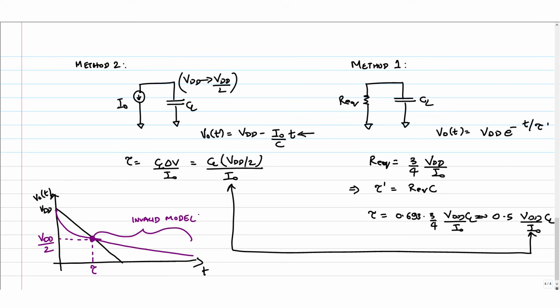The reason I am pointing this out is you will see that we use certain models in this course which are valid only in certain regions of operation. Outside that region of operation, if you ask me what the value of the model is, I would say I don't care because the model is not even meant to handle that region of operation. That's the point I am trying to drive home here, okay. Any questions? The other thing is, of course, later when I start putting transistors in series or in parallel, then it's very easy for me to reduce that network using series parallel resistance combinations if I know R equivalent. With the current source model, I cannot do that, okay. Any questions here?